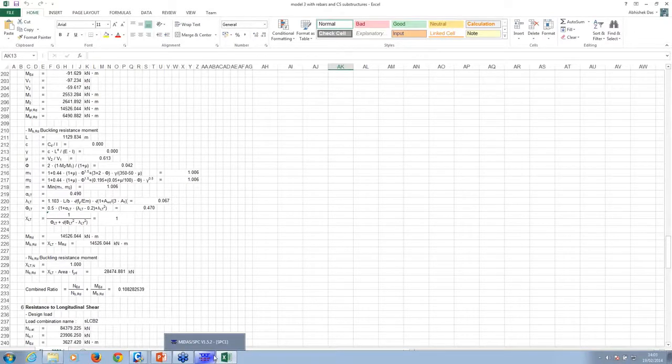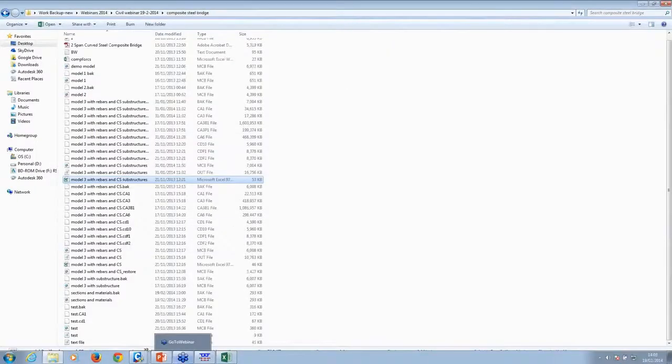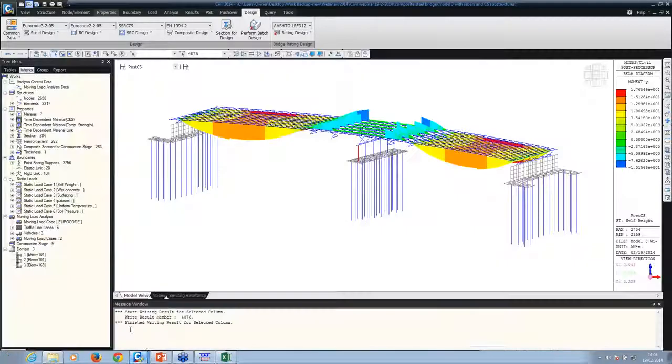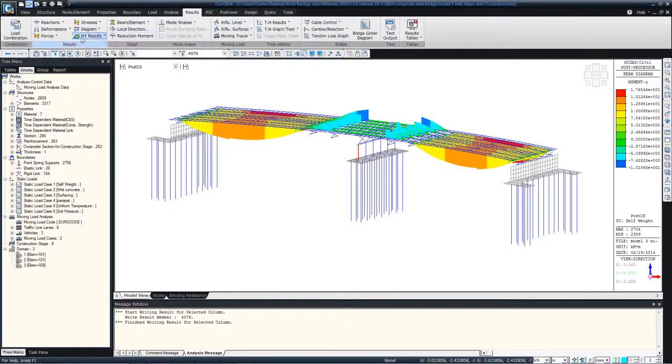Okay, there is another question. Can you show the beam and plate results at the same time? Because these are two different types of elements, so beam forces and plate forces, they are displayed separately. Beam forces and truss forces can be displayed at the same time because they are both line elements. But for the shell elements, you have to see it through the plate force diagrams. So that's where you see the plate forces, and you can then also sum up the plate forces to get the equivalent beam force.